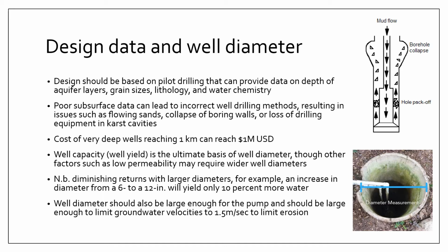Now, in terms of the size or the diameter of your well, this is mainly determined by the target well capacity, or the target well yield, or the target pumping rate of your well. All right. Although there are other minor considerations that are factored in the sizing of your well diameter, such as, for example, a formation with low permeability, right?